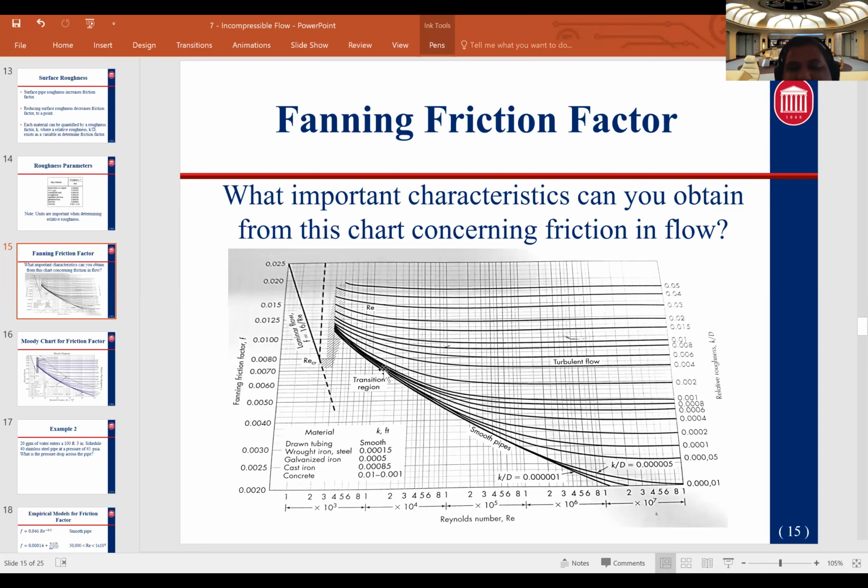Is everyone kind of seeing how I'm doing that? Oh, I need to shift it over. Never mind. Hold on. Let me double check that value. Nope, that is correct. So I went on my x-axis, I found my Reynolds number, and then I move up the y-axis until I intersect that relative roughness factor, which I do approximately here, which I would argue is maybe a little under 0.007, probably 0.0068.